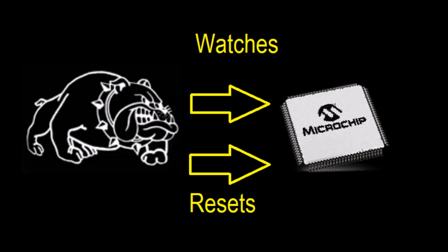One piece of advice is that in any embedded system, it is always advisable to use the watchdog, since no code is 100% reliable, especially when it is more complex. There is also the possibility, even if it is very small, that any electrical interference could alter the CPU's program counter, and it would skip an empty region or perform an erroneous operation.